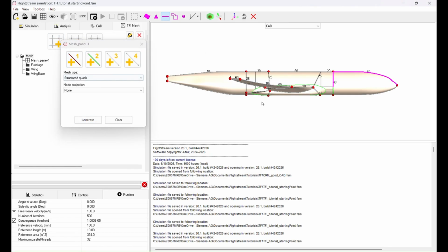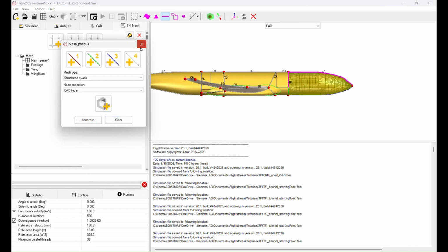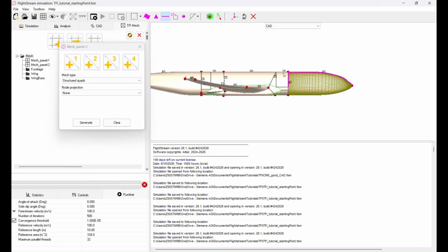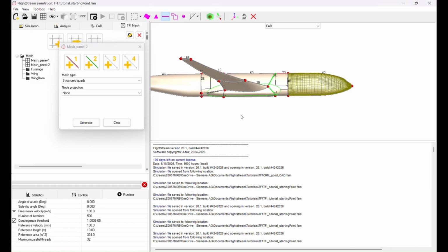Here we work with a 3-sided panel. Note that the 3-sided panel needs to have the first and third drawing curves meeting at a point, with the second drawing curve acting as the middle portion. Also note that you can select multiple curves per portion of the panel. As you can see with the second set, we have 2 curves that are on that portion of the panel.